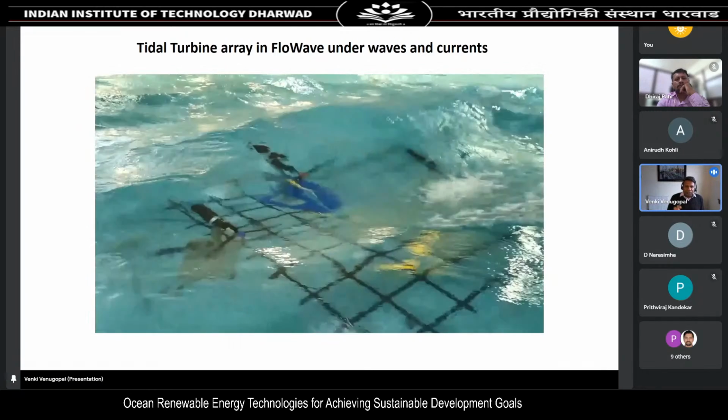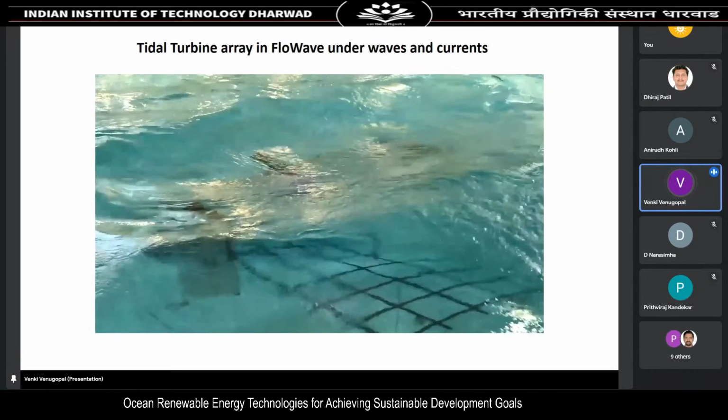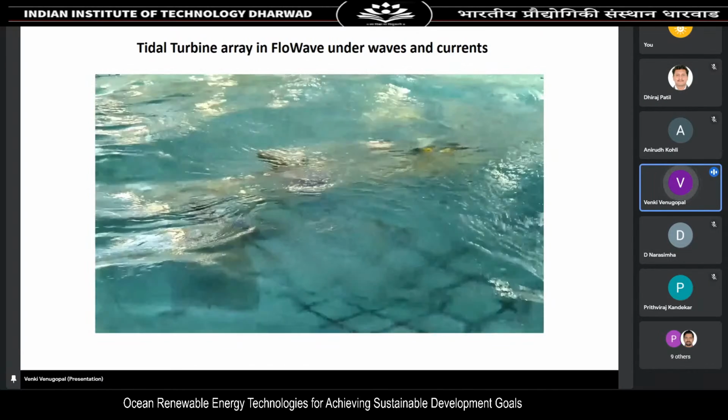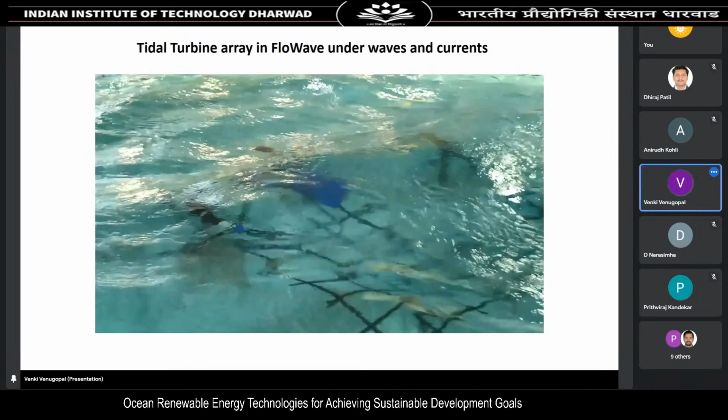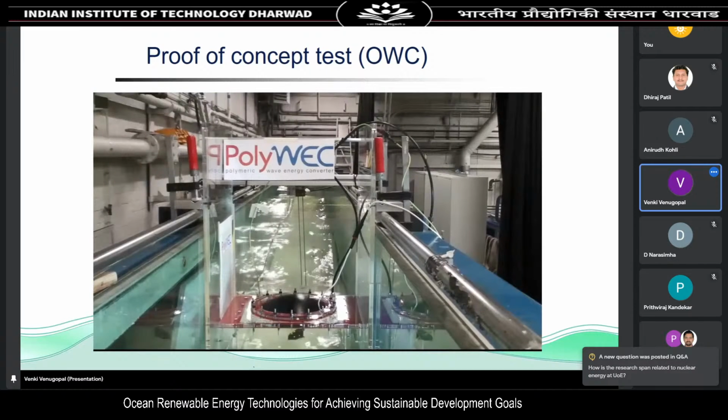The reason we do this is we study the scale model, and then we translate it into the prototype, which would go into the real sea. So we test everything, its stability, its strength, its failure criteria, everything is assessed in a small-scale laboratory study before it is made into a bigger prototype and then brought to the ocean.